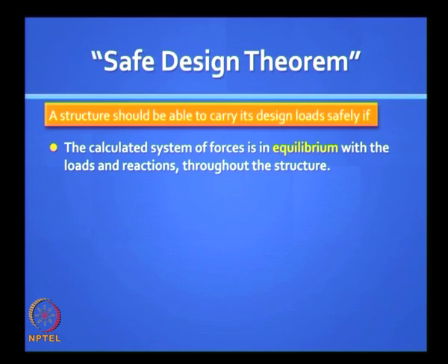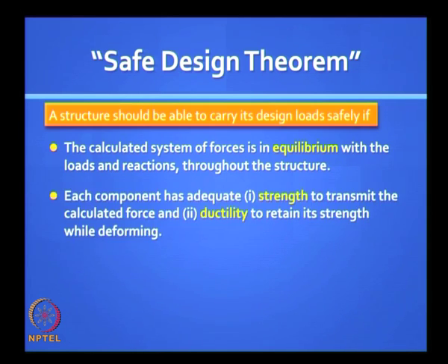The calculated system of forces must be in equilibrium with the loads and reactions throughout the structure, and should not violate equilibrium. Secondly, every component must have adequate strength to transmit the calculated force. So you get something from analysis, you get a bending moment, your beam must have that bending moment capacity. That should not be exceeded, otherwise your equilibrium solution is not valid.